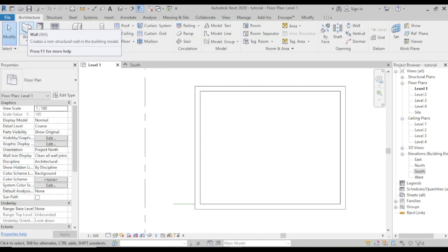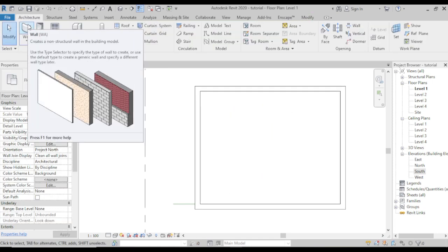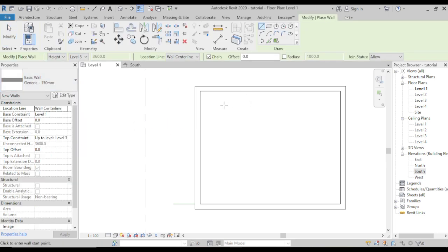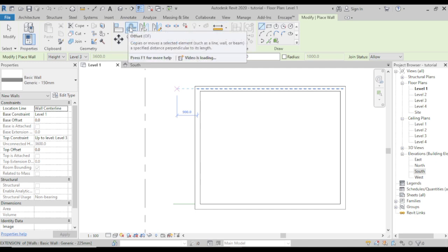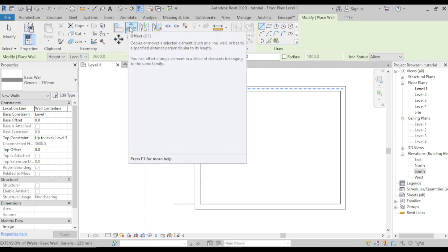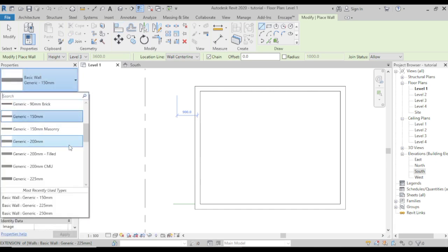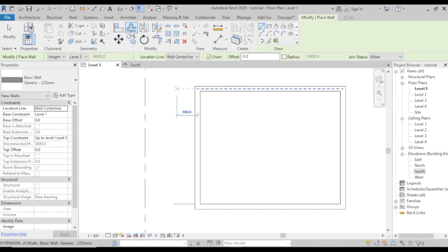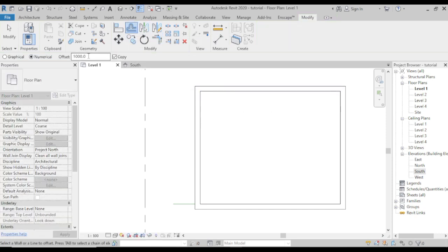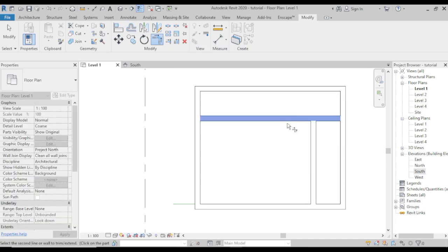We said we wanted to make one bedroom. There's a walkway. Oh, sorry, you can't see it, around this perimeter of the building. So we'll just do it this way. Let's click on this button. Where is the offset button? I want to recreate another wall, but not with this. 1,225. Okay, good. So click on offset and choose the number we need. Then click on this trim and extend button.